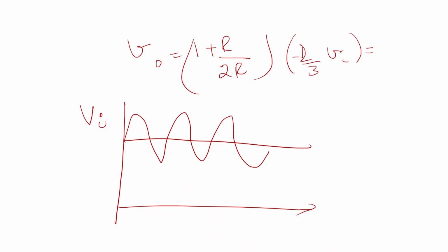During the positive cycle, the output voltage is negative. The negative voltage in turn is given to the positive terminal. Now the voltage at V0 is positive. During the negative cycle, the output voltage at V0A is positive, and hence V0A gives a positive input voltage to the amplifier A2, and hence the output during the negative cycle is also positive.